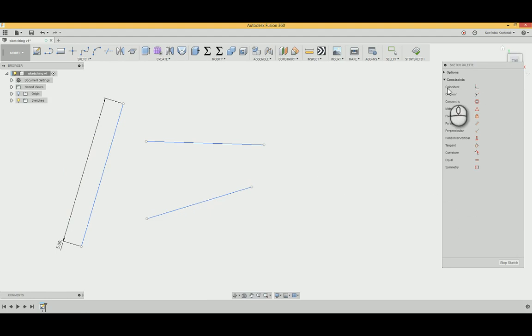So we're going to go through these constraints. The first one is coincident. That means you want a certain feature to occupy the same space as another feature. So what we do in coincident, don't click the word, click that actual icon symbol, and then you bring your mouse over, and you're going to see the cursor actually has the symbol of that coincident.